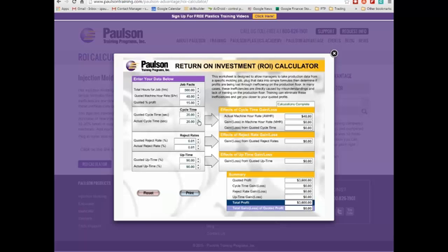So, just for simplicity's sake, let's say on average I can only mold this part at 21 seconds. Or maybe first shift and second shift do it at 19 and third shift does it at 23. At the end of the day it averages 21. So that single second in cycle cost me, you can see these numbers in red on the right, almost a third of my profit. In percentage-wise, that's 5%. So let's say my line speed was 5% slow over what I quoted, or my cycle time, as exampled here, is 5% slower than I quoted.